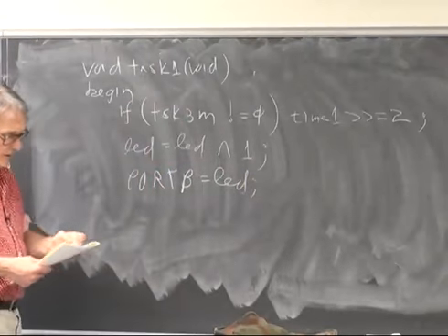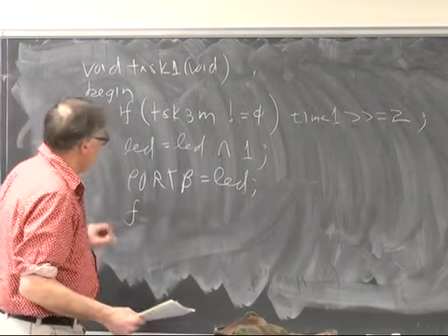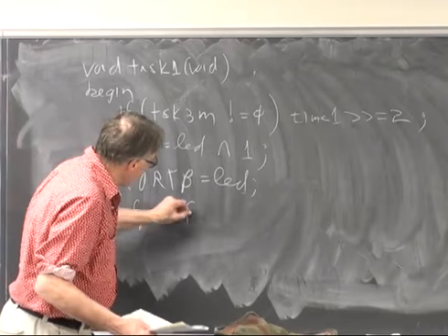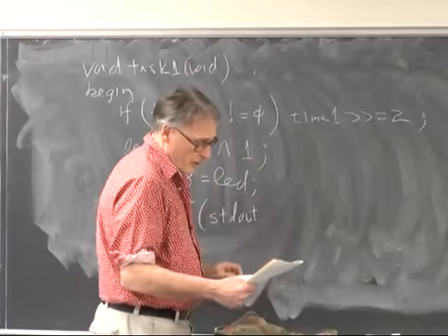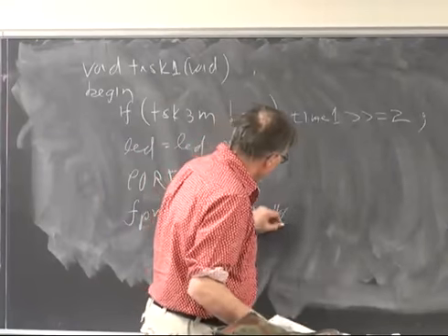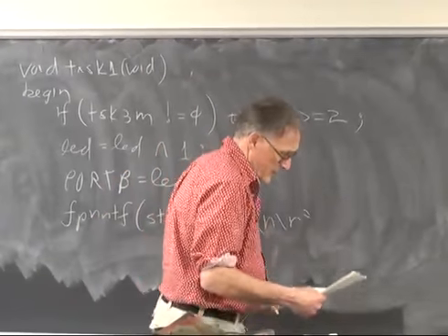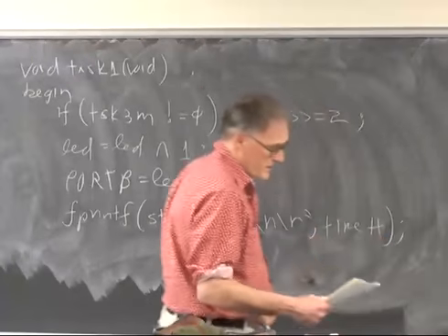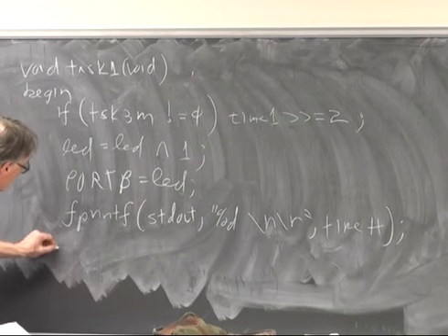And just for grins here, to exercise the serial function, we're going to do an fprintf to standard out, which is the terminal, with this cryptic string, %d \n\r end quote, and then the running time variable, which is time since reset, and then we're going to end.